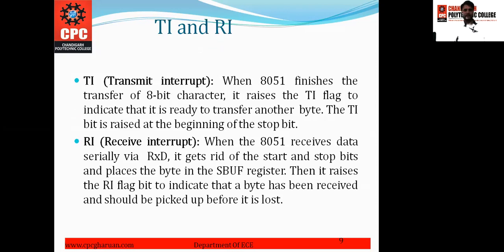Next is the TI and RI, that is the transmit interrupt and the receive interrupt. When the 8051 finishes the transfer of an 8-bit character, it raises the TI flag that indicates that it is ready to transfer the next byte. This is the indication signal that it has transferred the 8-bit character and now it is again ready to transfer another byte. The TI bit is raised at the beginning of the stop bit after the data.